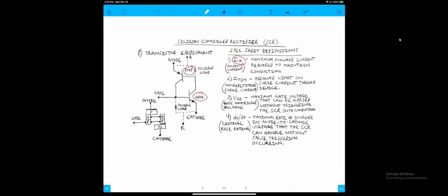The way this works is that once you throw that switch and start getting conduction through the circuit, through your SCR, which is what you're going to be building to represent the SCR, and you have enough current to light the LED, then you open the switch in your lab. Then you're going to see that the LED stays on. So the goal to begin with is to get enough current going through to trigger the gate, turn on the LED, and then throw the switch off.